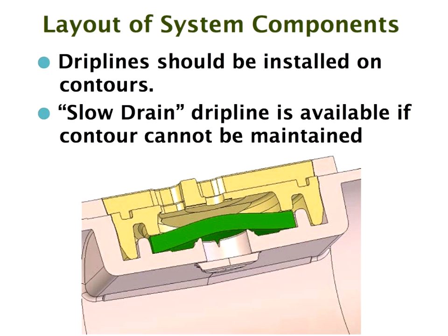And you can set up a vacuum that sucks dirt through the drippers that have already drained, the higher drippers. And this, of course, is going to ruin the dripper. It's going to plug the dripper by sucking dirt back. Sucking dirt back can be as frequent a problem as dirt being brought in from the effluent.